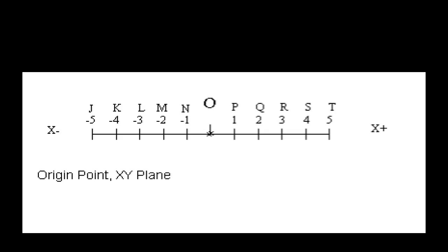We also know that if we want to go from X minus 3 to X plus 3, then we would actually have to move 6 inches: 3 to get back to the origin, and then 3 to get from the origin to X plus 3. As simple as that sounds, that's actually a pretty fundamental part of NC programming, particularly incremental programming, which we'll get into a little bit later. But knowing your distance and direction is very critical if you're going to properly position the tool around the part and make good cuts.